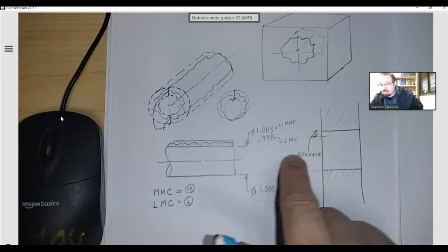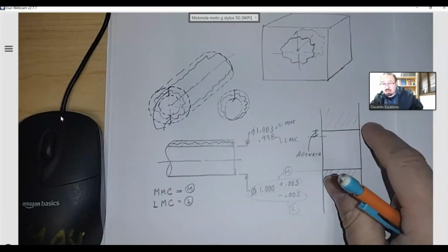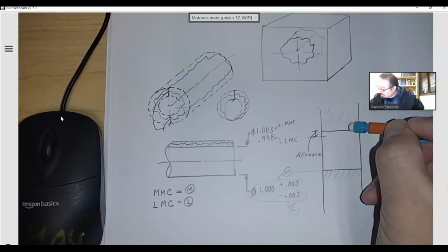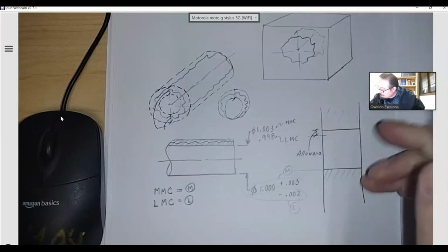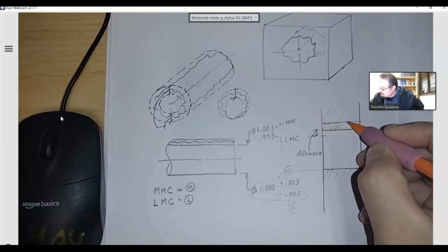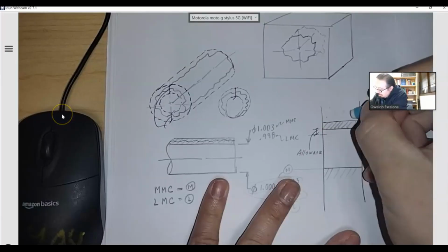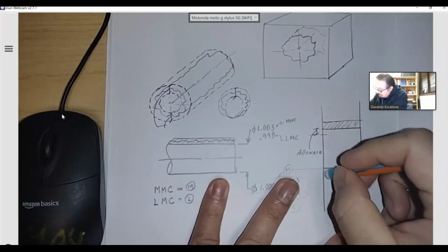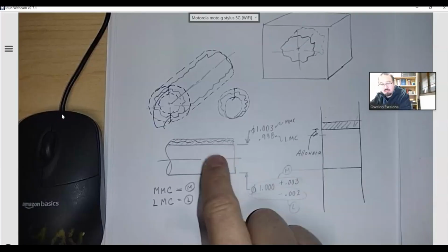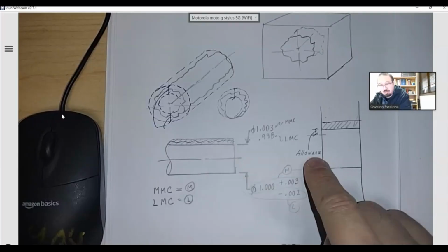it will always fit. Now, my hole also needs to have a tolerance. It needs to have a plus and minus. Okay, so what I'm going to do is give it the tolerance by making the hole bigger. See? So that means that when my hole gets manufactured, it's going to be bigger than what this guy already is, by a little bit more.